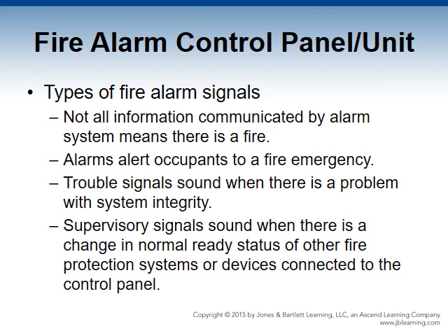Trouble signals sound when there is a problem with the system's integrity. It typically is a constant tone, beep, or buzz, accompanied by a visible light on the panel. Trouble signals are not alarms, but sometimes improper monitoring by personnel will initiate a fire department response. System problems should always be investigated and resolved as soon as possible because they can prevent the action of the alarm.